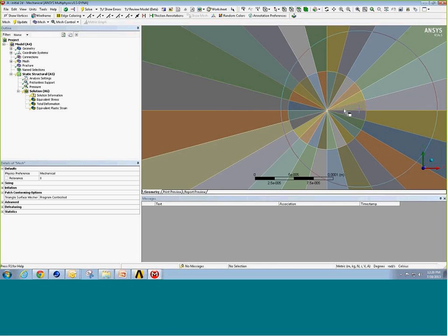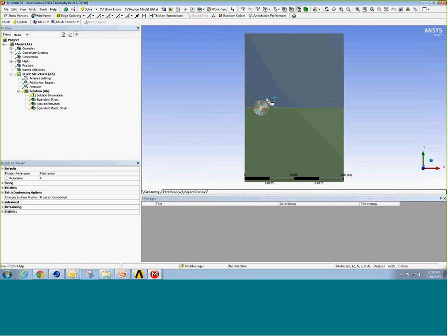I purposely made these cuts in Design Modeler because I want to make sure I have a nice mesh around the end. Now, ANSYS uses contour integration to perform all of these calculations. The contour integration doesn't require it, but it'll be much more accurate if you have concentric circles of elements emanating out from the crack tip.